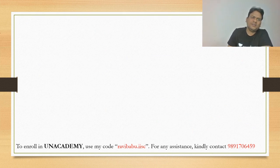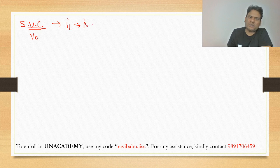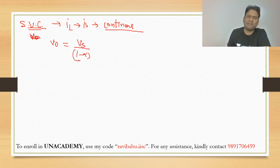Now for the step up chopper, when IL, which is also equal to the source current IS, is continuous, please mind it, V0 is equal to Vs by 1 minus alpha.